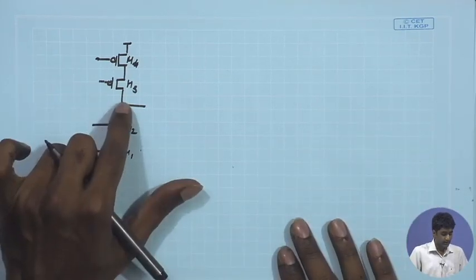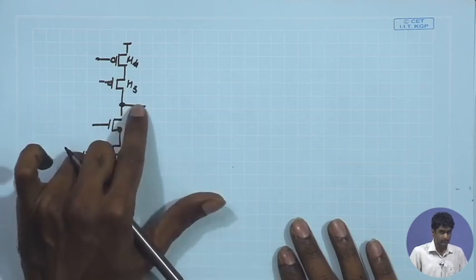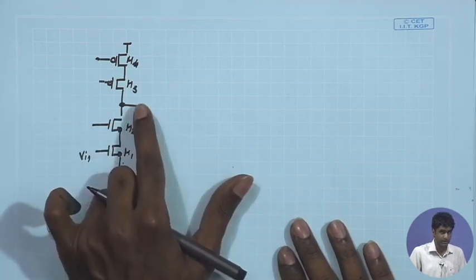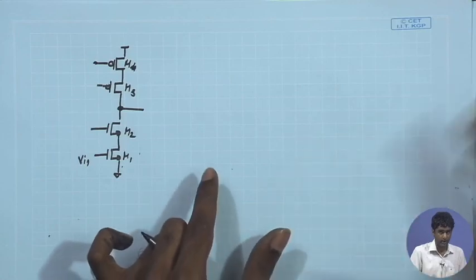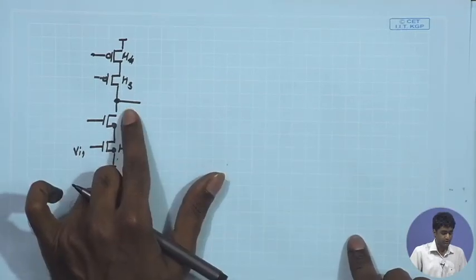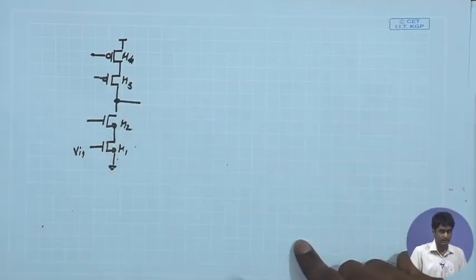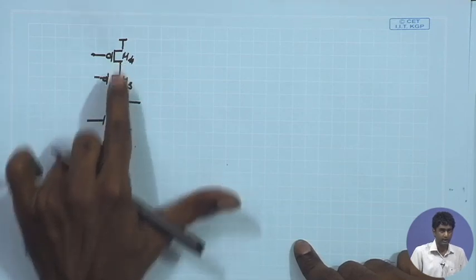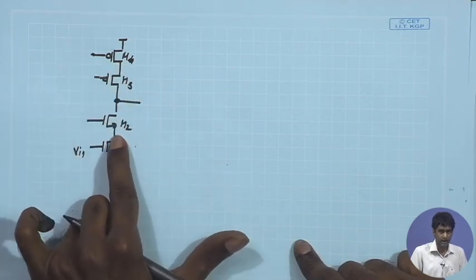We also looked at the poles. So here we saw that the output pole is going to be the dominant one because here the impedance is GM_RO square, GM times RO square, which is much higher than RO. As a result, this becomes the dominant pole. Other two are having an impedance just given by RO.